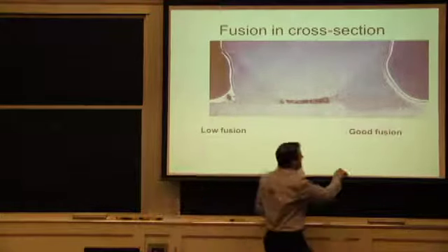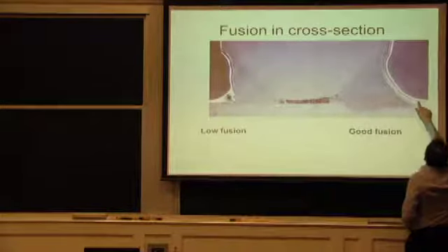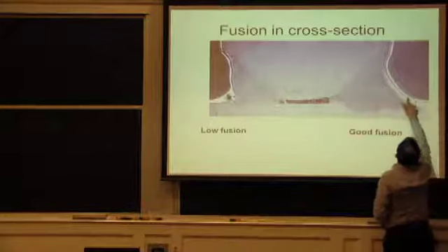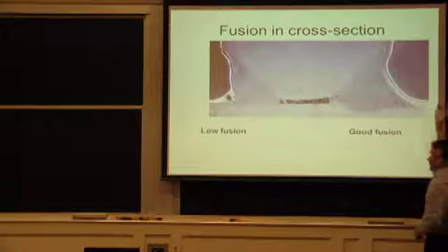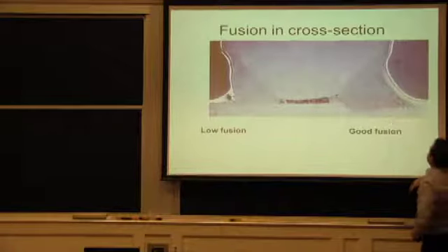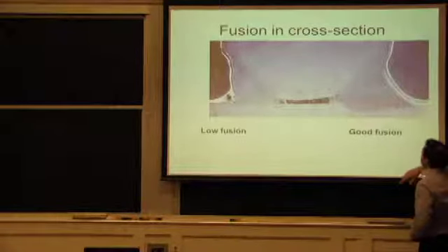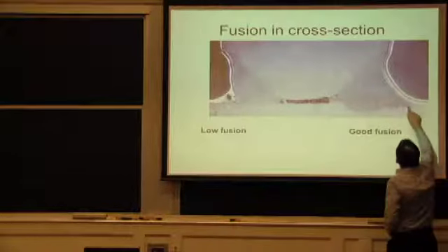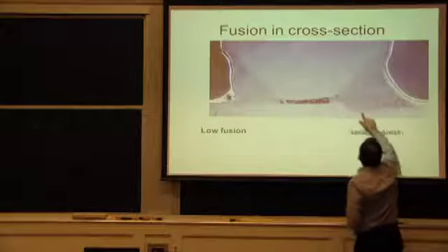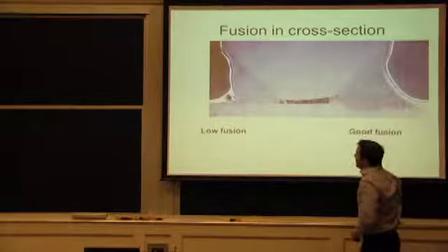And on the other side, you have one here where the contact angle, between this and this one, is probably 130 degrees. So this is actually a very high quality fusion. And it penetrates here. You see the line of the welded metal.